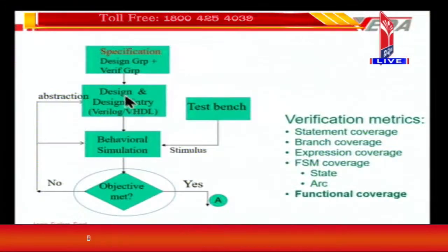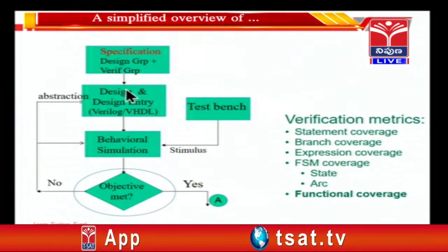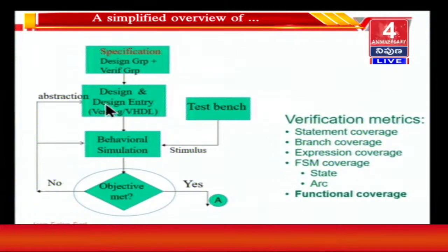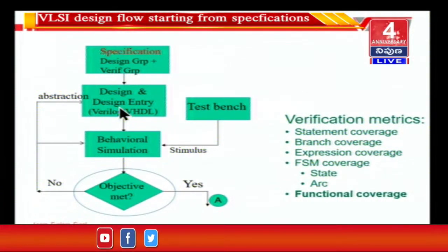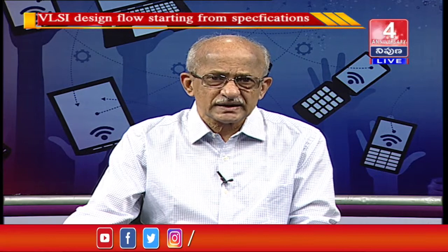Once the code is written to some extent, different blocks will be allocated to different people in the design team. They will write their own code, and their interfaces have already been defined. The designers also do what is meant by sanity level checking. That is, they write a simple test bench to check that their code is prima facie working or not. Once that is done, with some test cases, they will give it to the verification team for more exhaustive and extensive verification of that particular block.